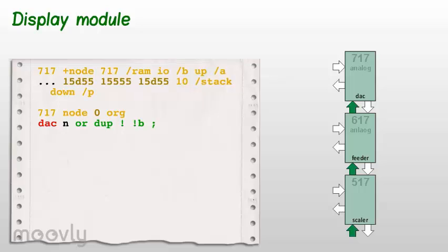The only effect is that the node suspends according to wake-up direction bit and continues when level on the shared pin has changed. Out of reset, wake-up direction bit is 0, so we wait until there is a high level on the shared pin. After wake-up due to level change on the shared pin, the node immediately stores the top of stack into I/O register, which sets DAC to a new voltage, and at the same time flips wake-up direction bit, so when we next time write into up port, the node will suspend until the level on the shared pin changes to low again.